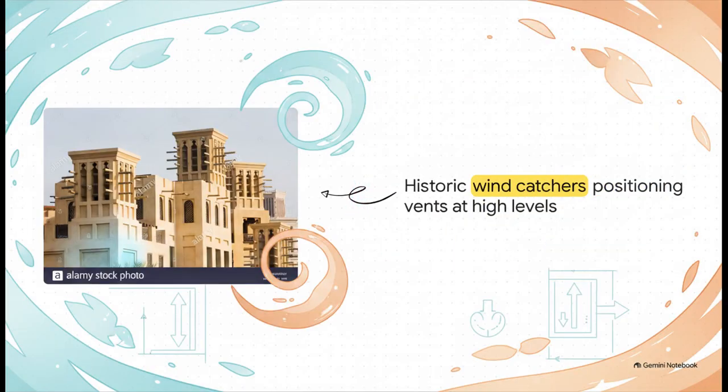But, fenestration is definitely not just a modern concept. Look at these historic wind catchers. They are absolutely brilliant, and they apply the exact same bioclimatic principles we've been unpacking today. By arranging these specialized window-like vents at extremely high levels, they naturally catch those prevailing winds to force heavier, fresh air down into the building while simultaneously venting out the lighter, hot air from the living spaces below. It is just a stunning historical masterclass in passive design.